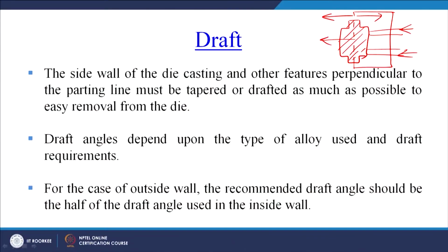Draft angles depend upon the type of alloy used and the draft requirements. In many cases we may not have a draft requirement, so no need to provide the draft in the product during the product design.